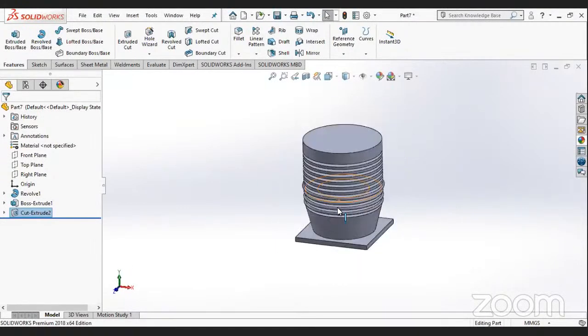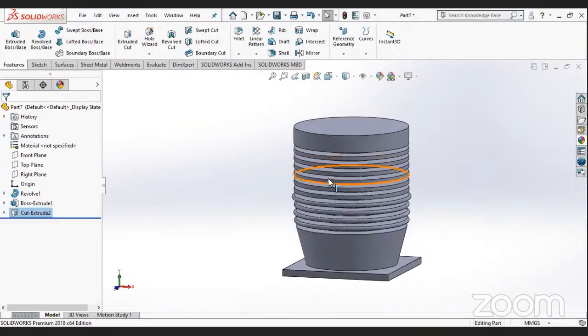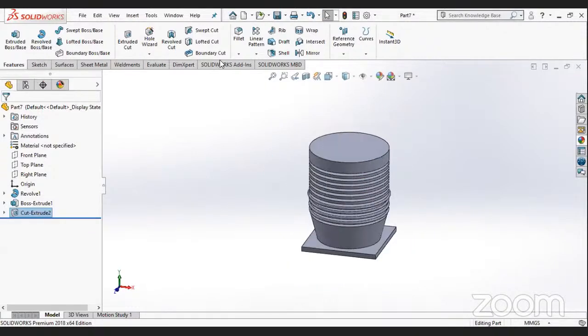Quickly we'll go in the upper side and make the upper part. We'll see the dimension for it. We have a fillet here which is 5 into 41.99 degree. So we'll just round figure it to 42 degree. So we'll go again in the fillet option.